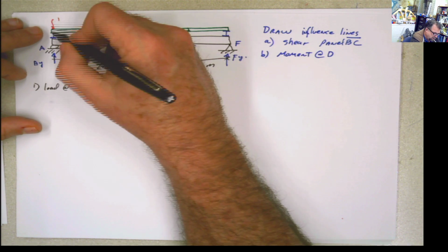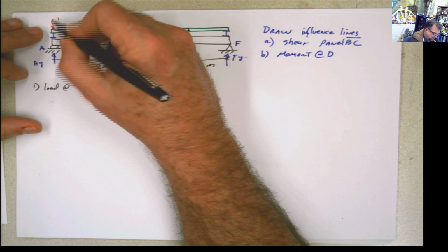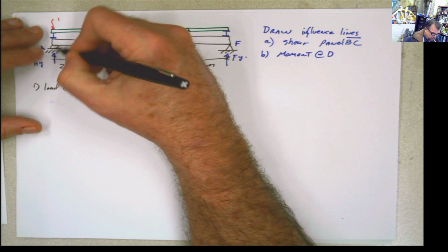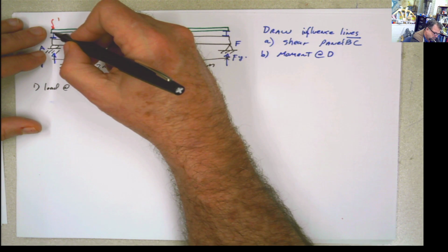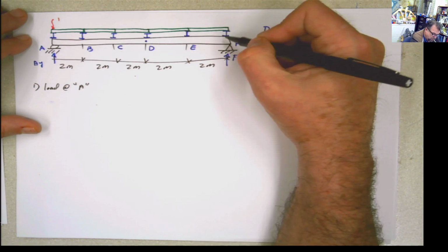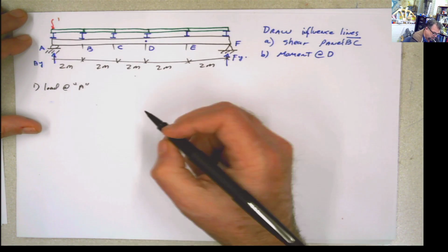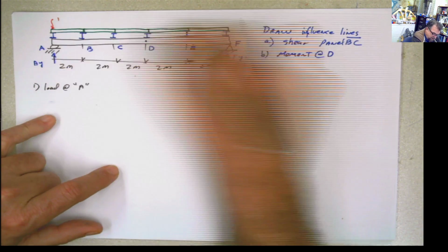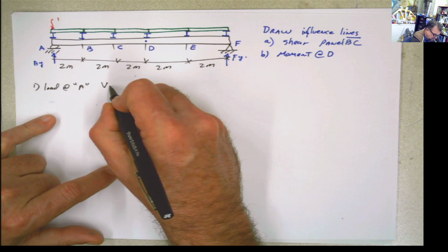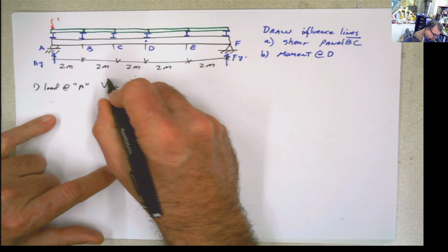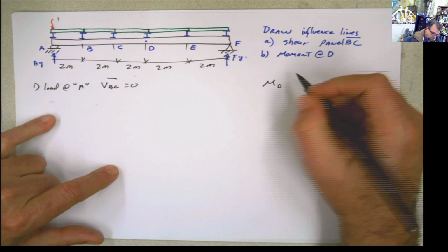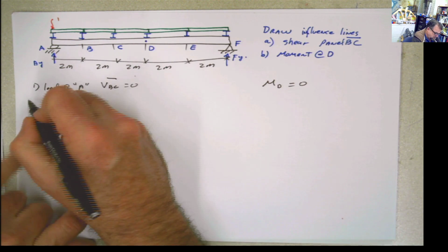Okay, anyway, you have that load over there of 1, and that load is acting on top of the support AY. None of that load is going to be applied in the girder itself, because it's absorbed completely by the support A. Meaning, whatever I'm calculating here is going to be 0. So the shear at the panel BC is 0, and the moment at D, which is the other question that this problem is asking, is also going to be 0.